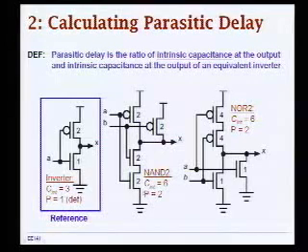And then we simply find the ratio between this reference case and our case over here. So we have 6 over 3, the parasitic capacitance of a NAND is equal to 2. Okay? And then the same thing for the NOR. Basically over here we have a PMOS and 2 parallel NMOSs, so the total parasitic capacitance is equal to 6.